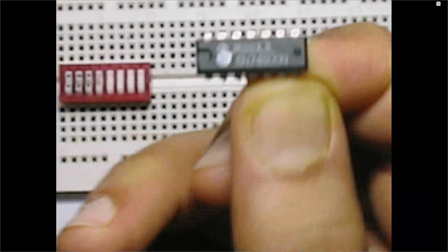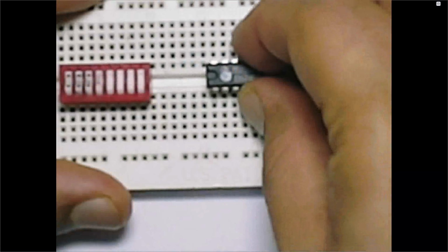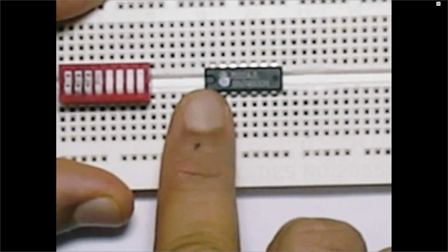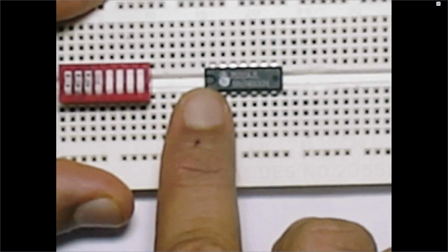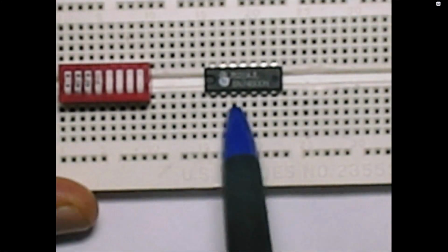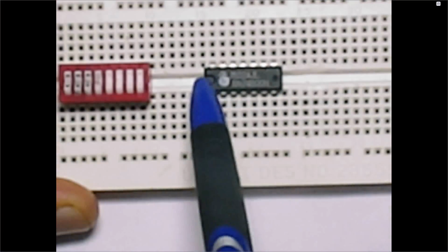That curve has to be on your left. So I kept it on the left, and I'm putting the IC here, okay? See, I put the curve here on the left. Now, you see the IC means you have some pins, right? How many pins you got? You actually have 14 pins in this IC: 7 at the bottom row, and 7 pins here, right?